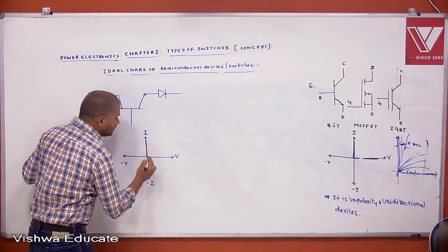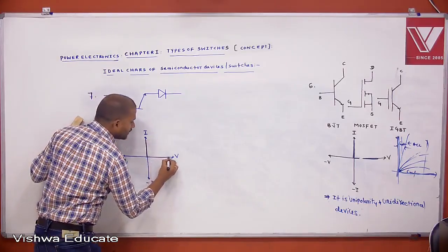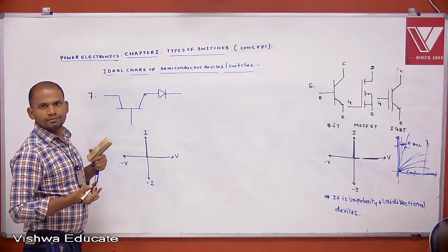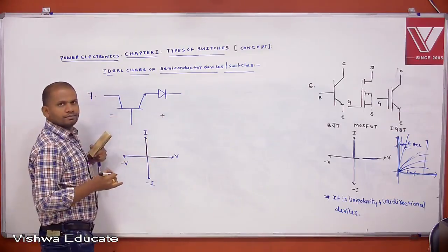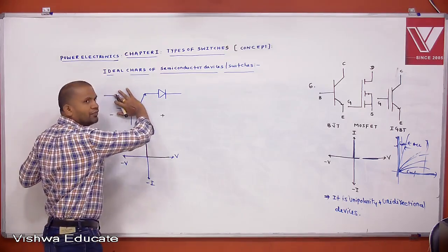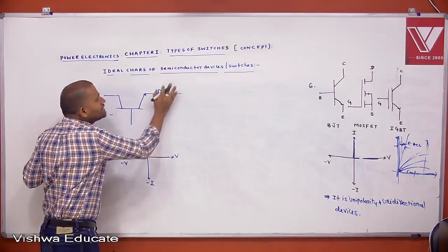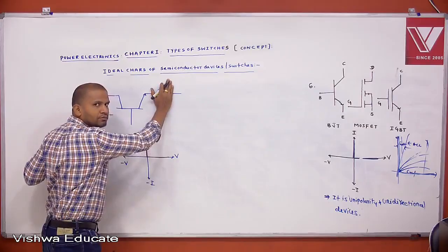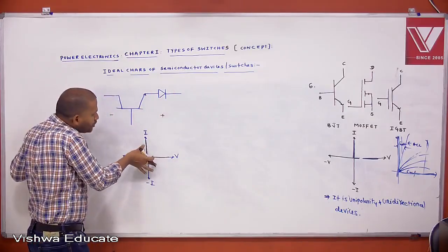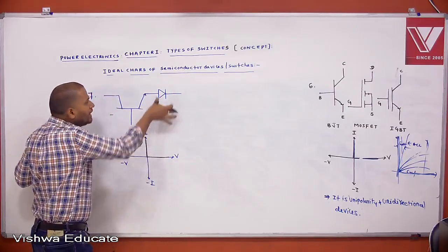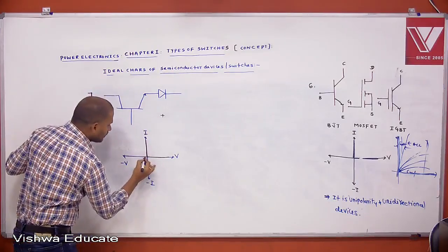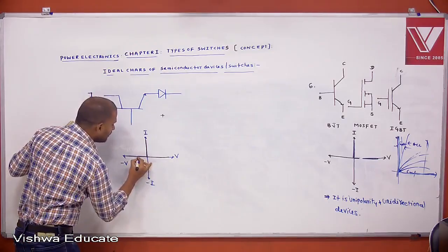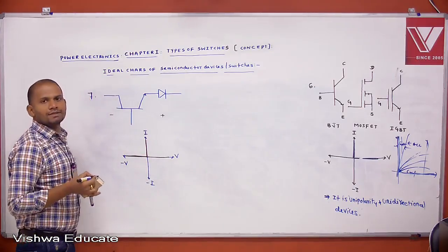Transistor blocks the forward voltage. If reverse voltage is applied, we don't have any blocking by the transistor, but this voltage is blocked by which one? Diode. That's why up to this, the transistor is okay. Because of this series diode, it blocks which voltage? Reverse voltage. Extra we are getting this characteristics.